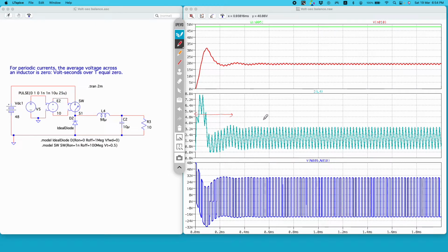Your circuit should reach steady state as fast as possible, and component selection should be proper. That is, you make sure that the peak value of current or voltage during transient is tolerated by your inductor, switches, and diode, whatever component you have in the circuit.